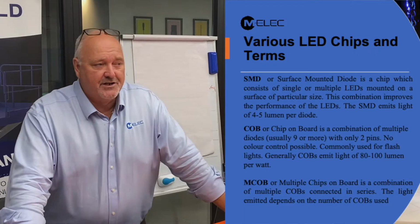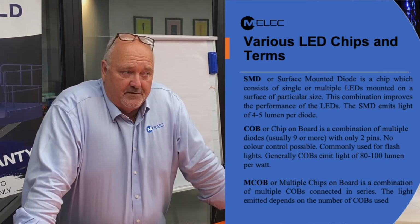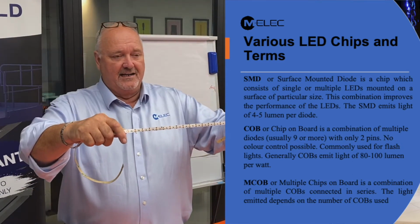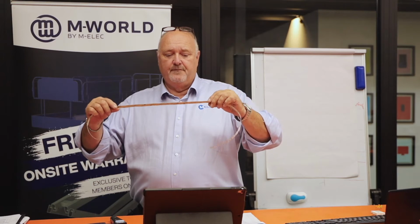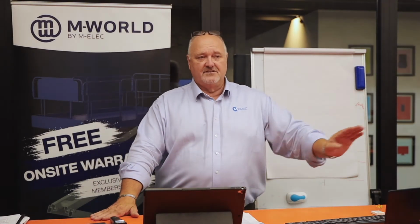A surface mounted diode is a chip which consists of single or multiple LEDs mounted on a surface of a particular size. Your classic surface mounted diode is on your LED strip. The LED strip is a printed circuit board, and the diode is attached directly to it. That's a single colour. You can get multiple colour: RGB, RGBW, RGBWW, and so on. That's a surface mounted diode, and it is efficient because of its design.